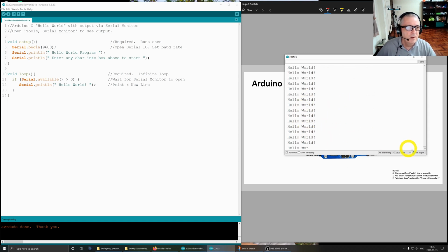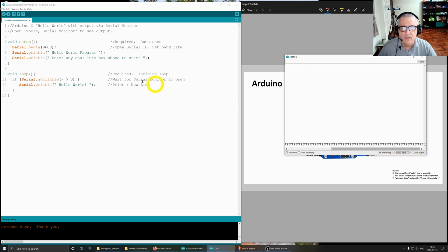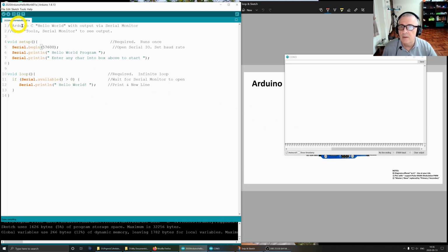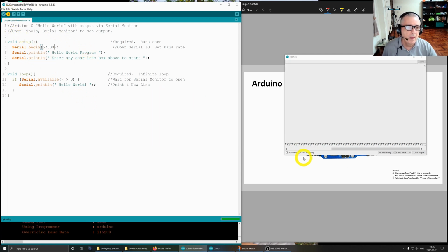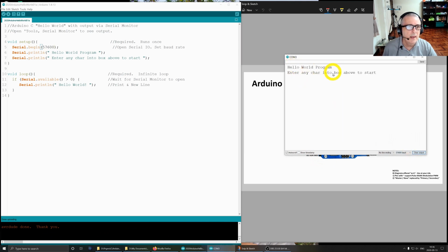Okay, let's take a quick look at this baud rate thing, and that's pretty much it. Let's change this. This will tell you the selections you have. Let's change it to 57600. Notice it stops working over here and it's confused. 57600. Then we shall recheck it, recompile it, and then upload it. And usually we'll get a line of garbage. Clear the output.